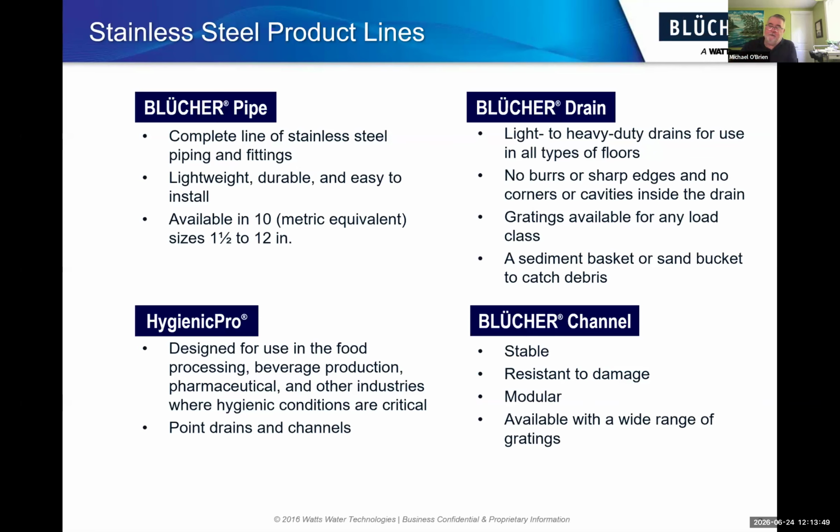And the other reason they do that is in these older cities there are issues with rats in most of them, and the rats can't chew through stainless steel. They can chew through plastics. They can find holes where cast iron has rusted out, and certainly where clay pipe is used leading up to servicing the building, then that again gives them access through the cracked clay pipes.